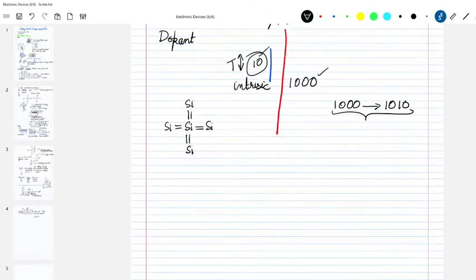Now what will happen is, if I replace one of these with arsenic, so now arsenic is bonded within silicon, and arsenic has 5 electrons, so 4 have bonded and 1 is free. So 1 additional electron is there per arsenic atom. Arsenic is called a pentavalent element, while silicon is quadrivalent. So you have a pentavalent here, so you have one electron extra per arsenic added.